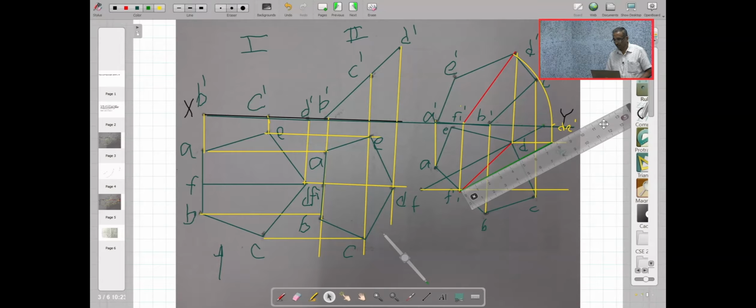So now we have understood the projection of planes as well as the projection of lines concept very clearly. We use this kind of process whenever in stage 2 you are not able to see the true length, you are having only apparent length, but what is given in the problem is the true angle. Then we have to find out this apparent angle using the procedure told to you.